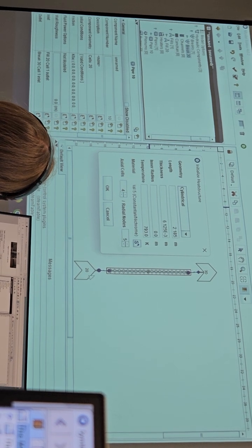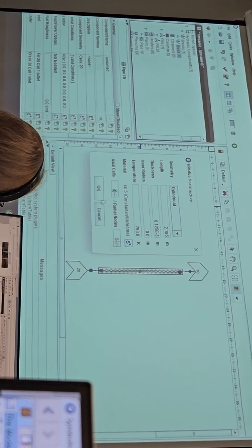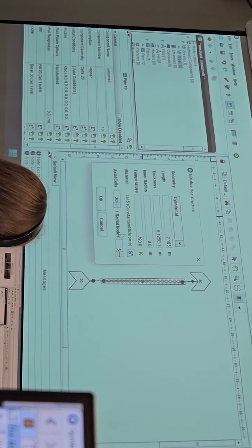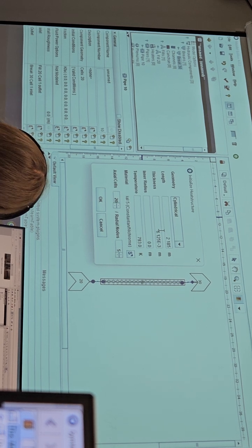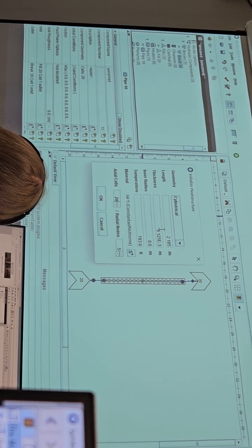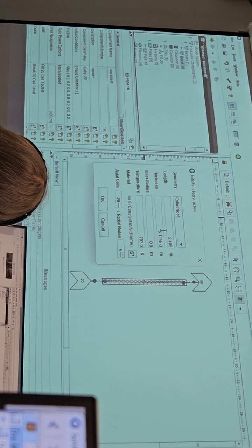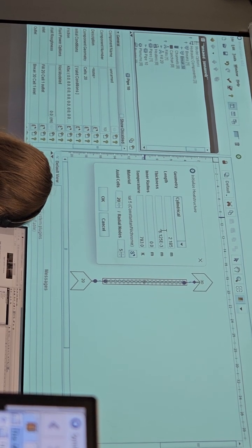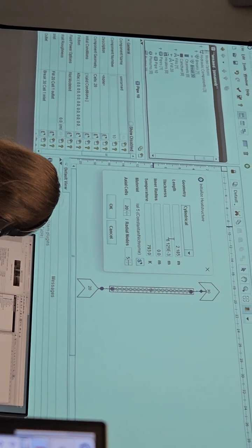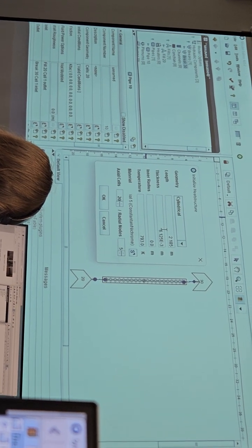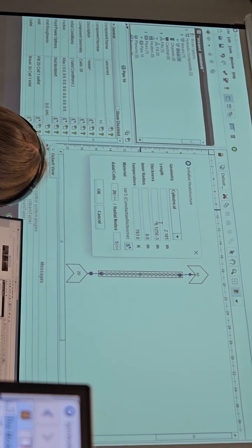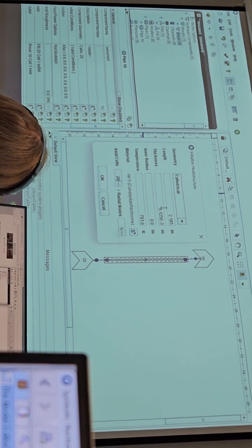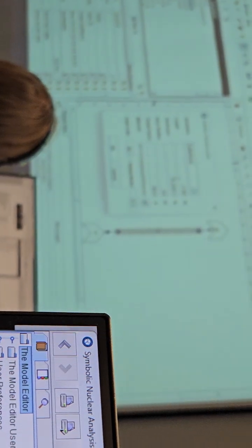Since we have a pipe with 20 cells, we need to make this heat structure with exactly the same amount of cells. Radial nodes depend on the accuracy you need in your case. You can check the temperature of the fuel rod, for example, inner surface, central surface, and outer surface. If you have just one radial node, it will be more or less homogeneous temperature across the whole fuel rod. If you divide the fuel rod into 5 radial cells, it will be layer by layer temperature. It will take into account the thermal conductivity and so on.